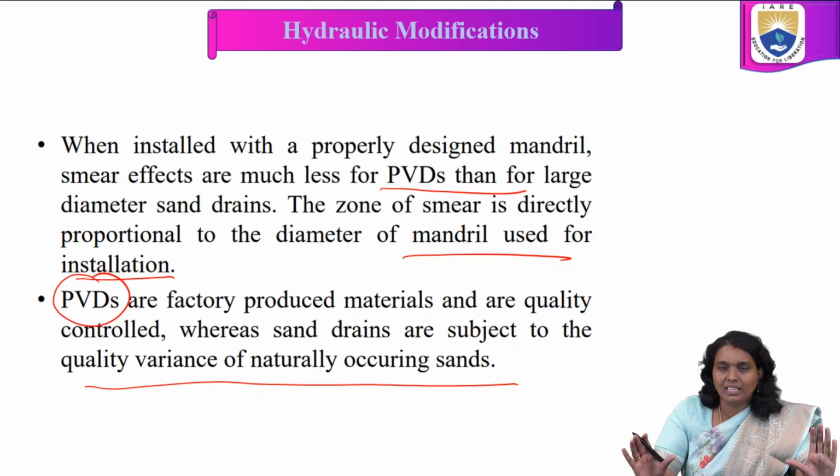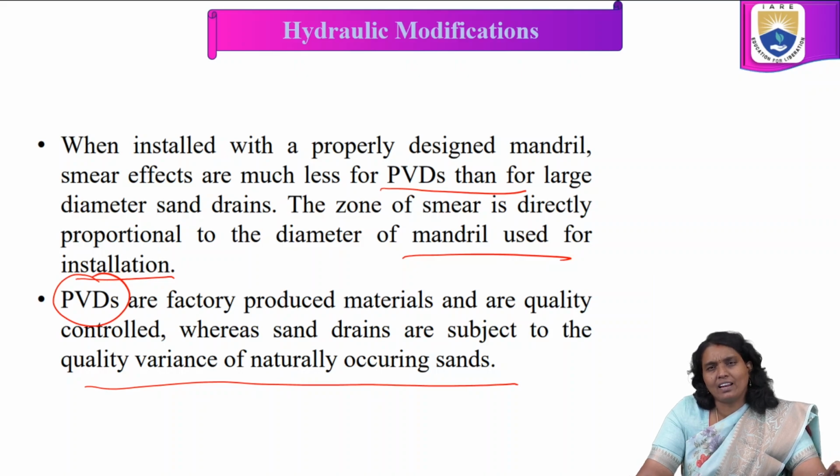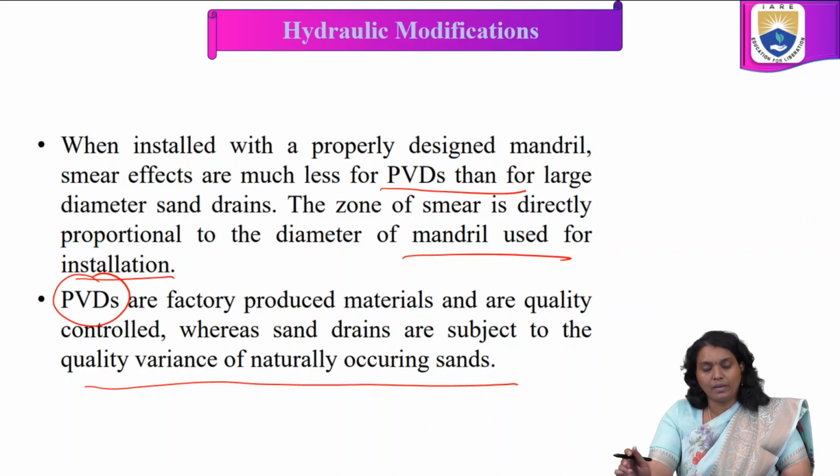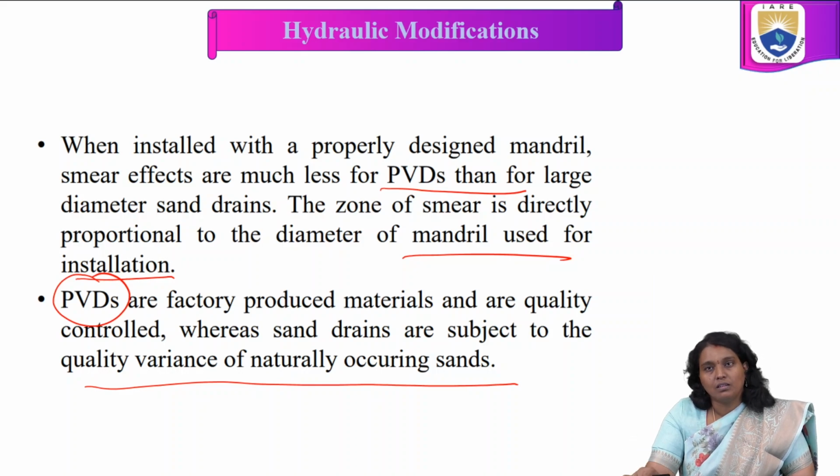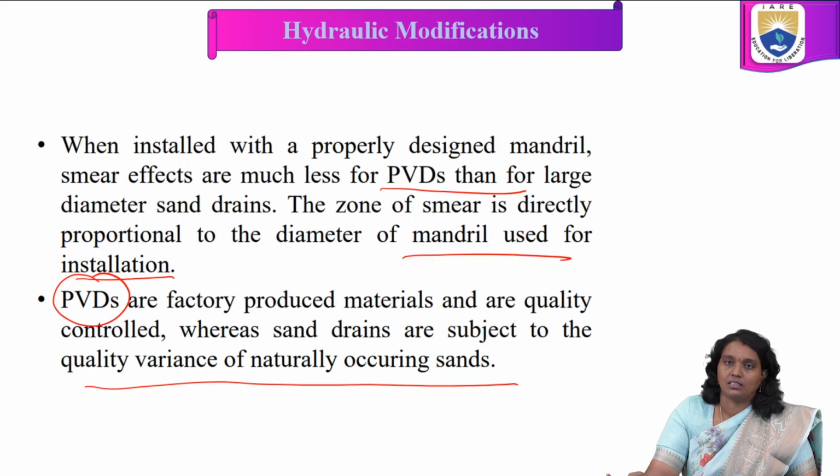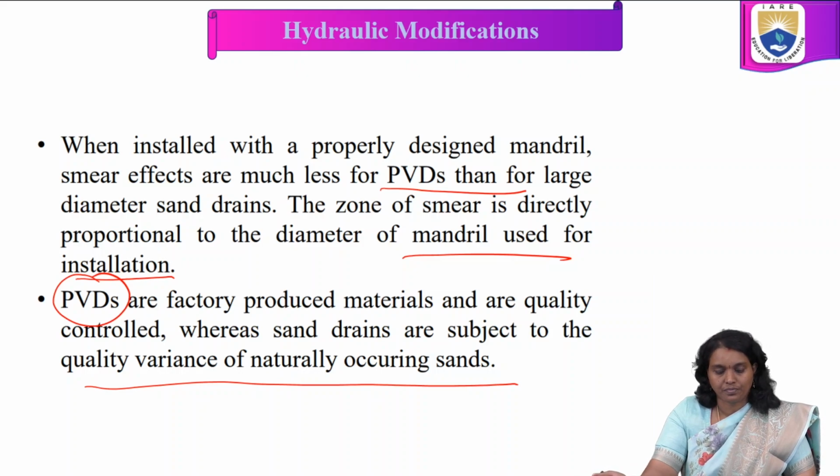Whatever the required size, material or strength, we may control it. We design these PVDs for the required properties from the quality point of view, whereas with sand drains that is missing, because they are naturally occurring sands. These are the advantages which we observed in wick drains.